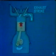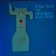This final stroke in the cycle is the exhaust stroke. The piston again is pushed up in the cylinder, and the cylinder is emptied of gases through the open exhaust valve. The cycle then begins again with the intake stroke as the piston completes the exhaust stroke. The entire four-stroke cycle takes 2 revolutions of the crankshaft.